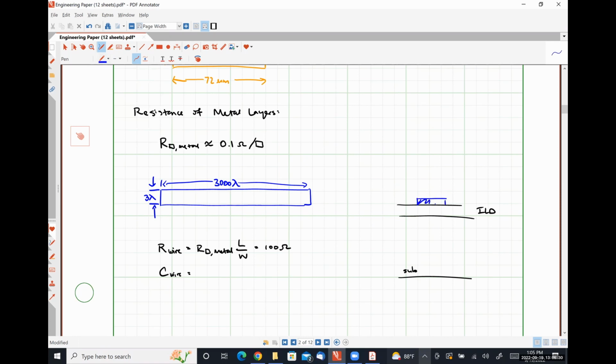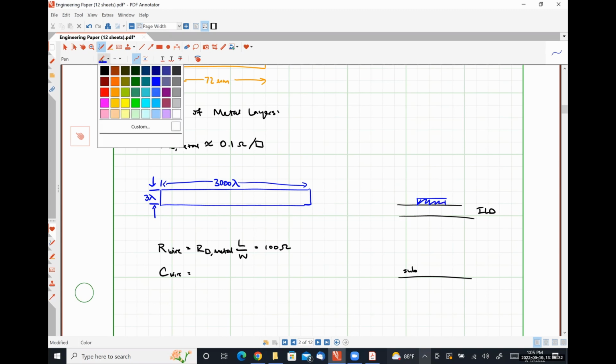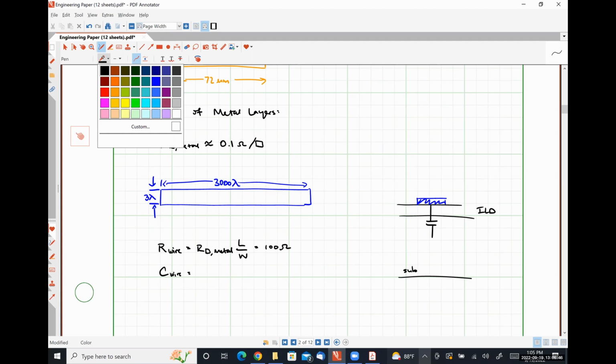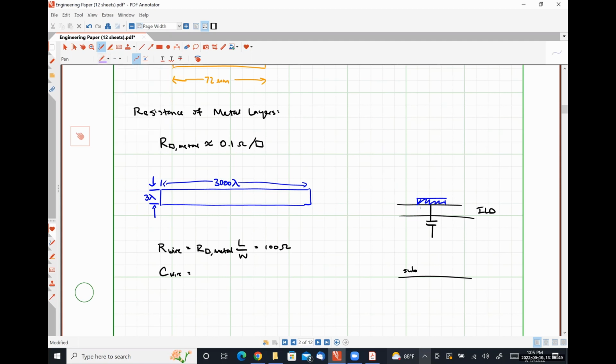And then we have our metal 1 layer. We have a capacitance formed between the bottom of the metal 1 layer, where we have effectively, let's use light pink, nice, well-behaved electric field lines being oriented directly down. That's giving us our area capacitance.